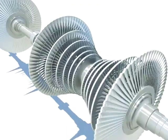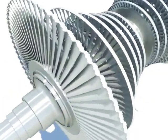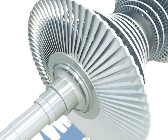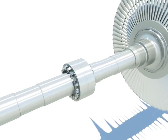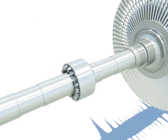The bucket is assembled to the turbine wheel part and works for changing heat energy from the steam into turning motion by conveying it to the shaft. Also, it changes the fluid flow by using the entrance and exit angle of the bucket. The coupling is an equipment which connects two rotative shafts and is fixed with uniform and solid high tensile bolts.